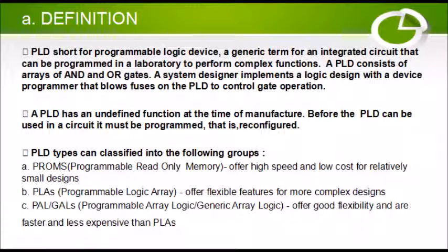The definition of programmable logic device: PLD, short for programmable logic device, is a generic term for an integrated circuit that can be programmed in a laboratory to perform complex functions. A PLD consists of arrays of AND OR gates. A system designer implements a logic design with a device programmer that blows fuses on the PLD to control gate operation.